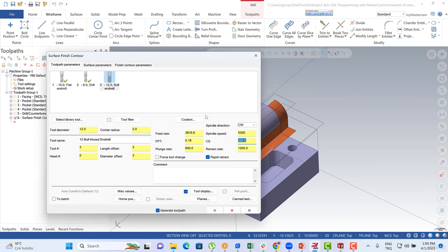But if you use this one as a cutting speed, your tool wear is going to be better than with the 200. So this is the best way to see less tool wear in your process. But of course that also reduces our feed rate.